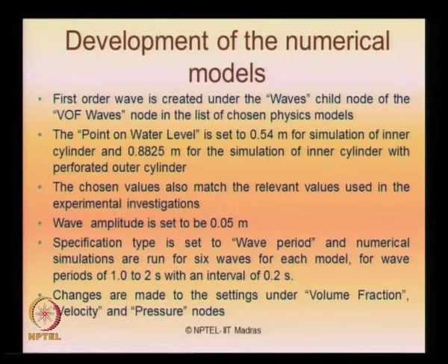The first order wave is created under the wave's child node of VOF models. The point of water level is set as 0.54 meter for inner cylinder and 0.8825 meter for the inner cylinder with perforated outer cover. The chosen values are matching with the relevant values used in the experimental studies, as I showed you in the table in the last slide. The wave amplitude for the numerical study is set as 0.05 meters.